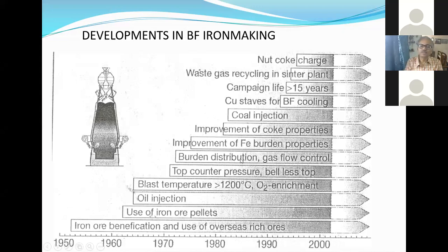You know, where to place the coke, where to charge the ore, because you know that coke has a low angle of repose and the ore has a very steep angle of repose, because ore is usually very heavy, and where it falls, at that point it tries to form a ridge. Okay, angle of repose is high, but the coke basically rolls down. Anyway, so those things are there. So where you put the coke, where you put the ore, that is very important. So burden distribution plays a great role in the gas distribution in the blast furnace.